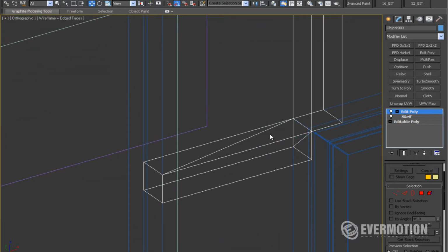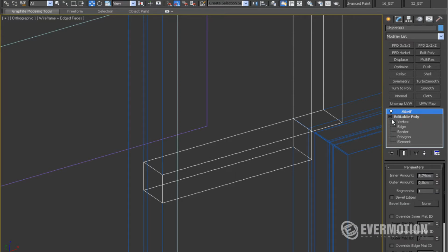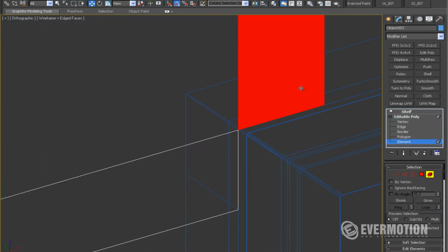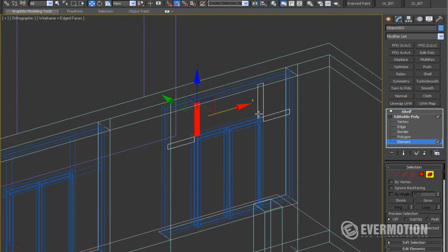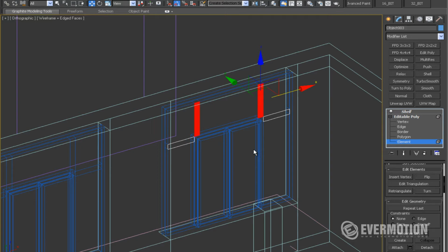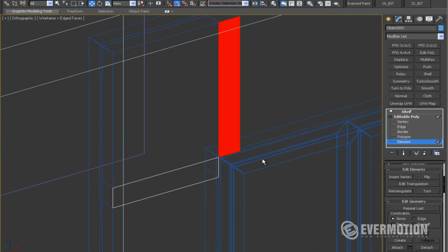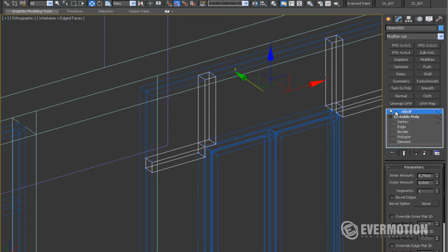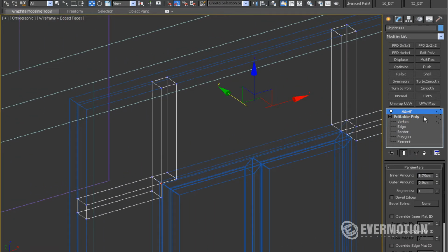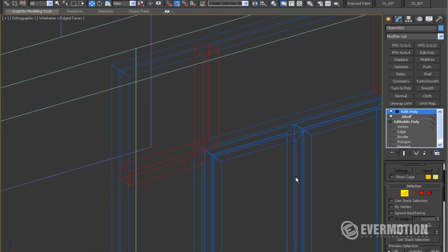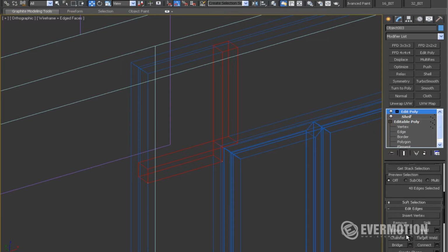We are having a small problem with the mesh here, because we've used shell on the object that hasn't been detached properly and has one vertex connecting two objects. So let's correct this. And now, after detaching, we have two vertices in this place, so it's correct, and we can use editable poly. Like in the previous object, let's chamfer the edges.